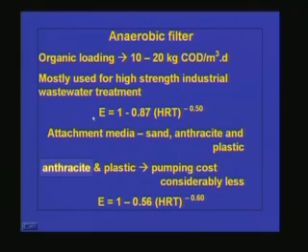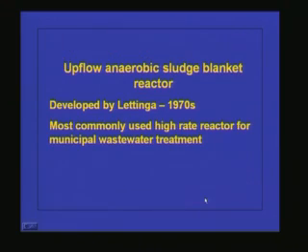Now coming to the expanded or fluidized reactor, I have already mentioned that the attachment media is usually sand, anthracite and plastic, and usually anthracite and plastic are preferred nowadays. The reason is the pumping cost can be reduced considerably. If you want to find out the efficiency of an expanded bed or a fluidized bed reactor, we can use this empirical formula: E is equal to 1 minus 0.56 HRT raised to minus 0.60.